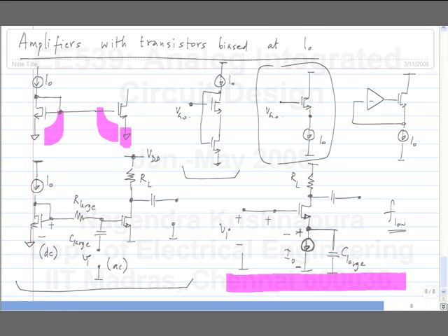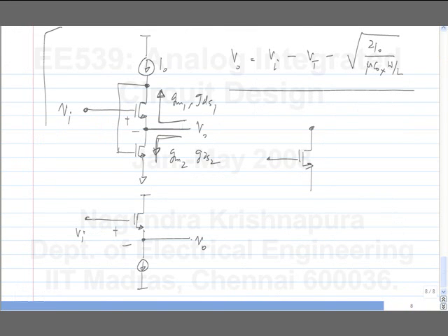So we now know the basic amplifier structures, and we also know how to bias them in a way so that the amplifier parameters are relatively insensitive to process and temperature. We know that biasing at a constant VGS is not a good idea, right? At least biasing at a constant current seems to be a better idea. Whether it's the best, I don't know. We started the course by saying we want to make negative feedback amplifiers. So we can finally come to that. Before that, any questions on the biasing arrangements as well as amplifier topologies using this type of bias?